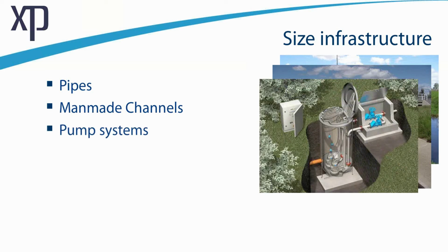An option that is rarely used, I suppose, in a stormwater sense, except in very specific applications, are pump systems. Obviously most engineers would be familiar with pump systems in a sanitary or sewer environment, but there are many instances where dewatering applications require pump systems to again apply additional energy to that water body or column, and one of the important elements in designing those kinds of systems is understanding how the downstream infrastructure resists the performance of that pump, particularly as velocity does increase in an enclosed environment.